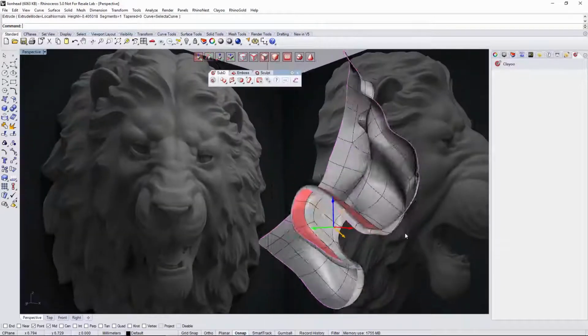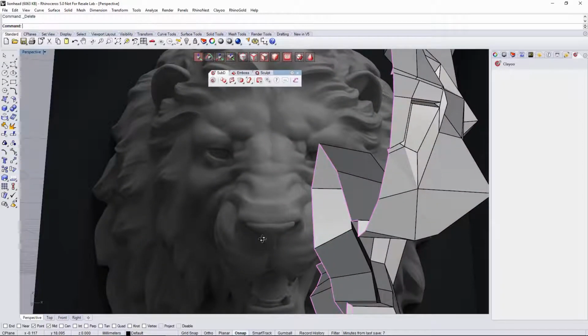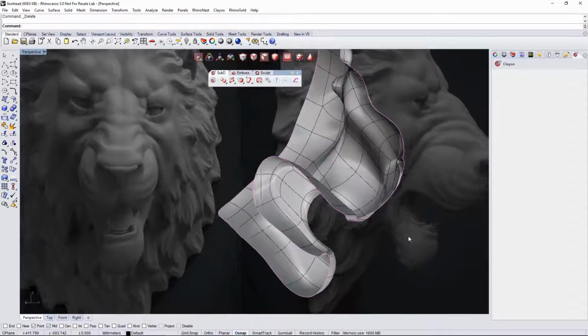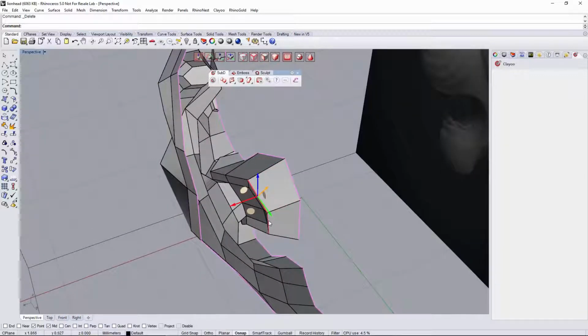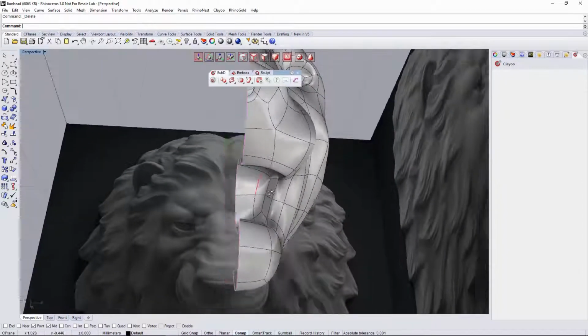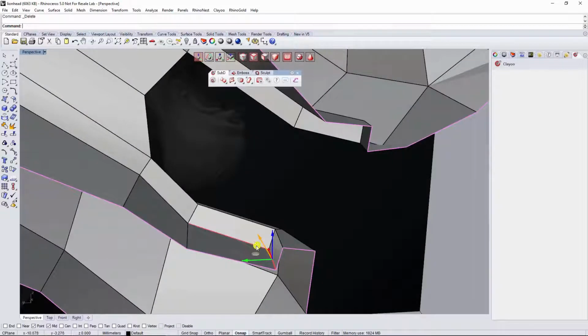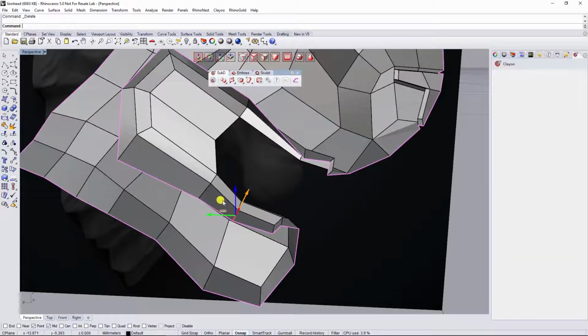Okay, let's right click, and now I'll have to make sure that I get rid of just the inner ones. So select all the inner parts and delete. Okay, perfect. Now I can refine a little bit more the shape if I have to, or refine maybe these 2 edges in here like that, so we have more rounded edge in here. But it's quite good. Refine a little bit this, so it goes gradually.